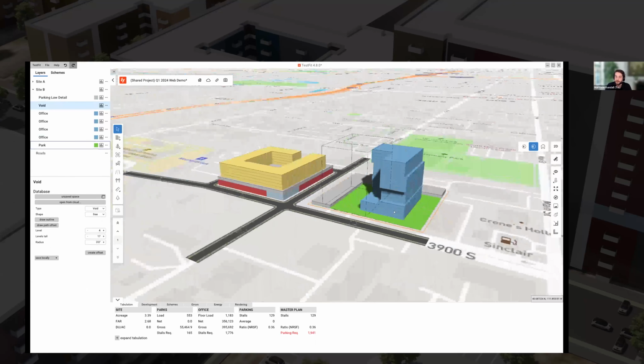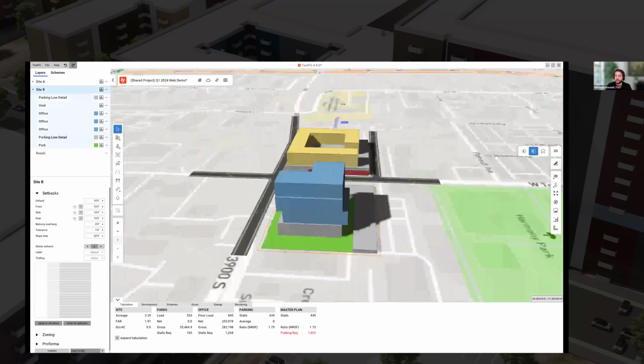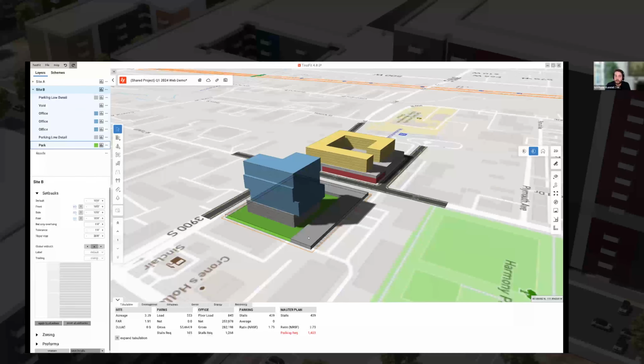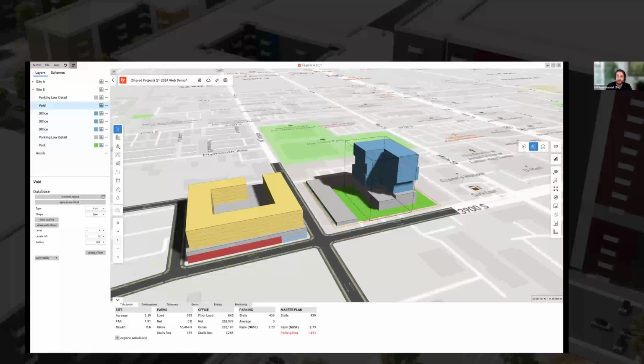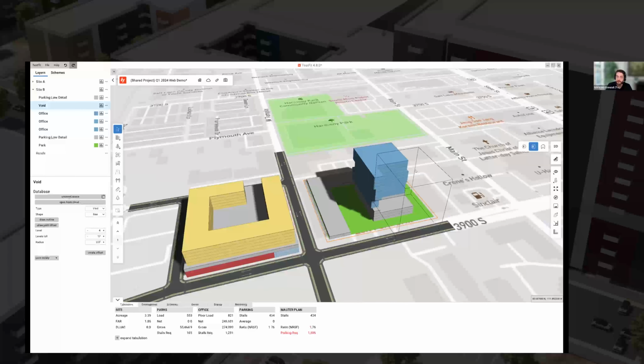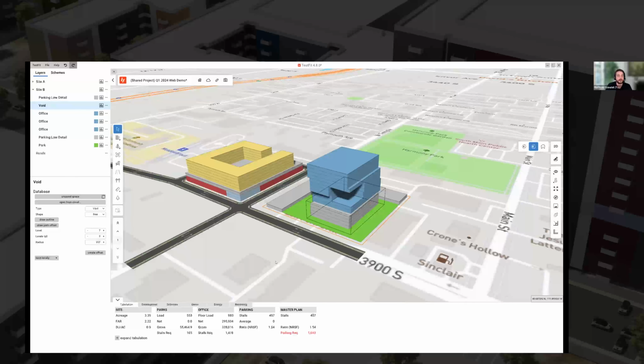We can start to change other elements. Maybe this ground floor isn't office. We're showing that kind of surface style parking over here. But as needed, I could change this over to a low detail parking. And now we're getting this idea of stacking the building with a garage. We're working with these void spaces to start to carve out a larger massing as needed. And this can even be reduced down if we wanted to create a hole or an inset within that area itself.